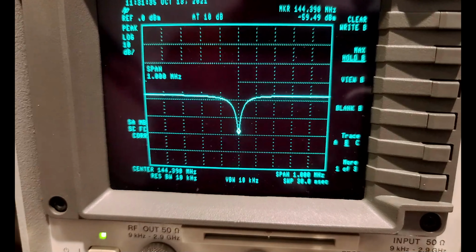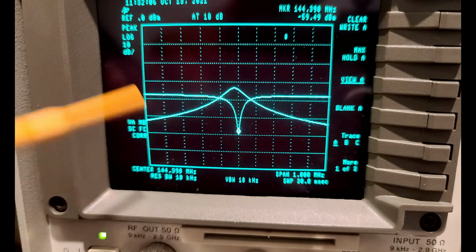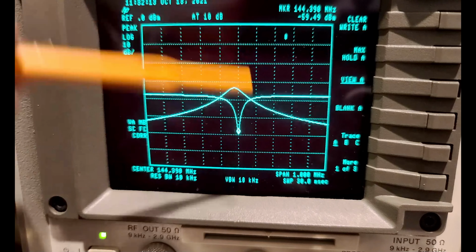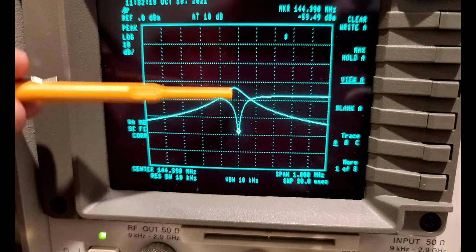I'm going to go back to my tracking generator, turn off the tracking generator for now. But okay, so what you're seeing now is the output from the trace hold. This is not real time. What you're seeing is the snapshot. But I'm going to go back to trace. Earlier on, I had saved in the A slot the transmission loss snapshot, and in slot B we have the return loss snapshot. Now, as you can tell, in the transmission loss we were off a little bit. This was before we readjusted right now.